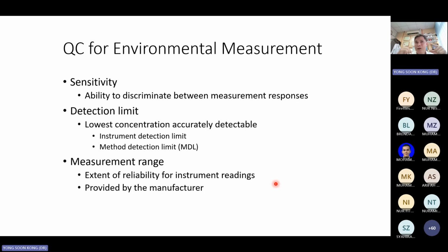Now, you have to have an expectation. You need to have a prediction. For the river water, roughly what is the pH? Roughly what is the DO? Since Sungai Tua is a healthy river, the pH maybe is not too acidic, not too alkaline, maybe around 7, neutral. Whereas dissolved oxygen should be high. So if the dissolved oxygen is high, even if your detection limit is a bit low, it can still detect, right? So there you go. For the probe that you're going to bring, if the river is healthy, the DO should not be a problem, right?